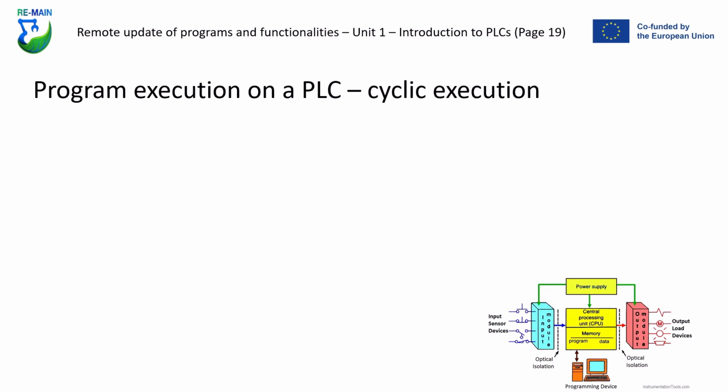In the previous slide, we have said that the PLC will spend most of the time in the cyclic task. So let us have a look at what exactly is happening in this task. One cycle is divided into 4 steps or scans.